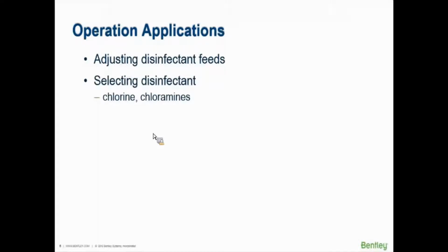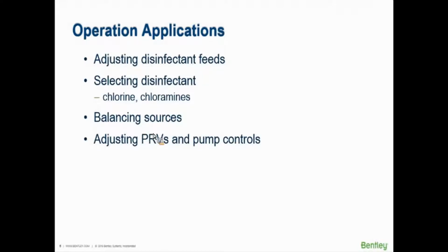You can create different disinfectant constituents to model, let's say chloramine or chlorine. Balancing water sources with total dissolved solids. Maybe you're adjusting PRVs and changing how pressure zones are operating to ensure adequate operation and movement of flow. So there can be quite a few different operation standpoint things that you can answer with the model.